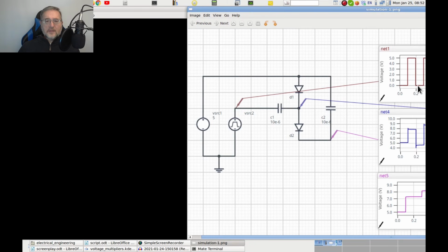This time, both C1 and C2 are charged and have already a certain voltage at their leads. Because the left end of C1 is now connected to ground and the right side is connected to the constant generator, its voltage will go back to Vin, minus the drop caused by D1. In the meantime, D2 is now off, because the voltage at the anode is less than the voltage at the cathode, which is the voltage of C2, and therefore there will be no current going in or out of C2, and its voltage will not change, as well as the output voltage.